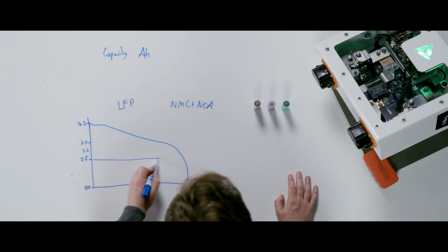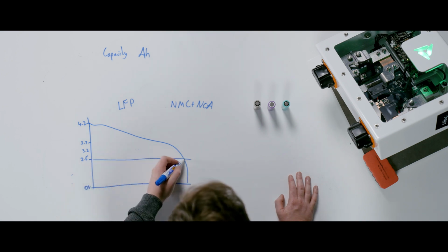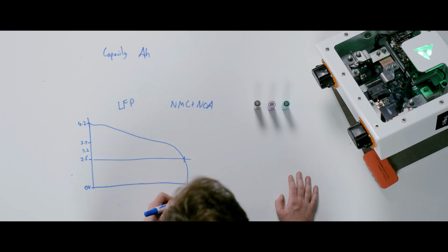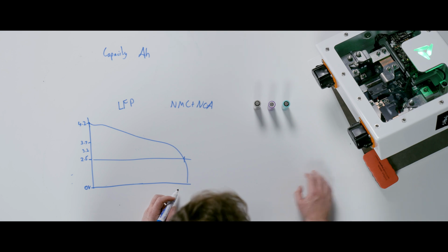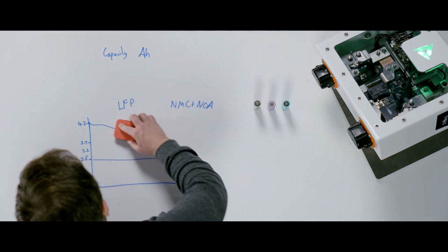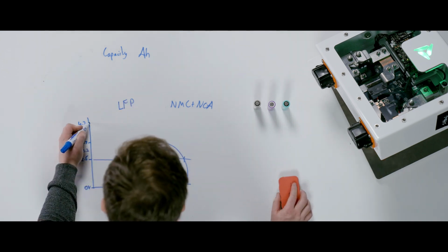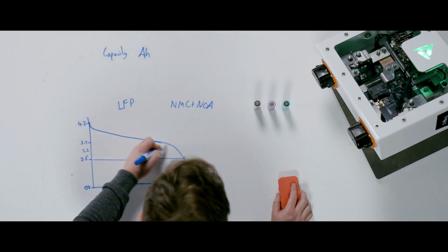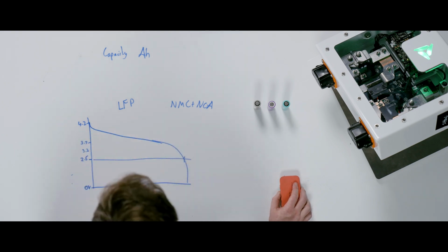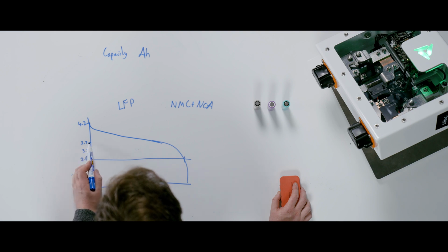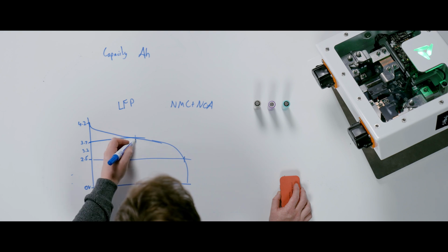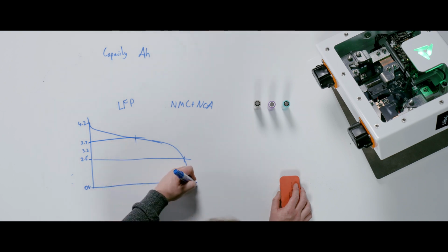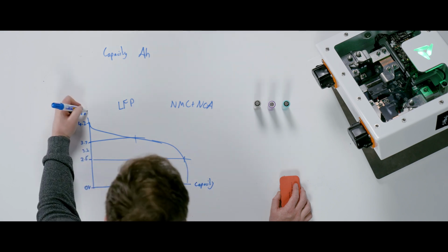where the battery is defined as fully empty down at 2.5 volts. It's completely full at 4.2 volts. And in fact, some chemistries can be a lot steeper than that, with a quick drop off from 4.2 volts and then linearly dropping down. We say that the nominal voltage of a battery is 3.7 volts because most of the average capacity is here. So this is capacity and this is voltage.